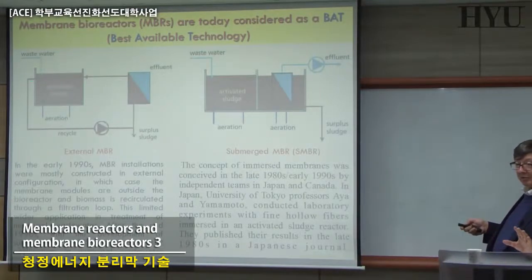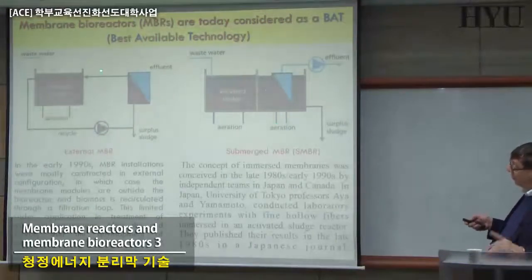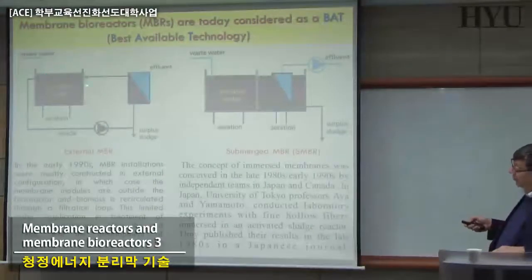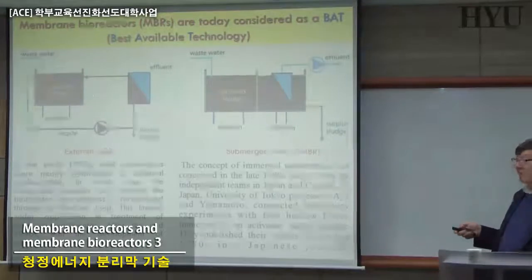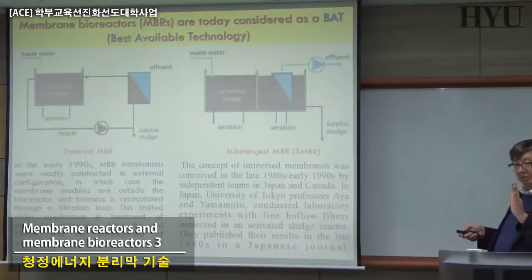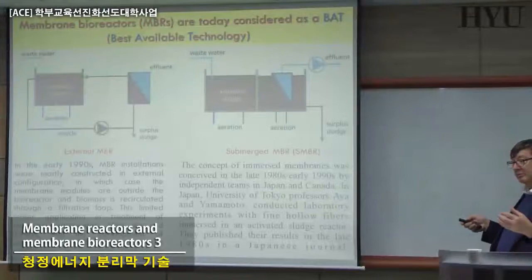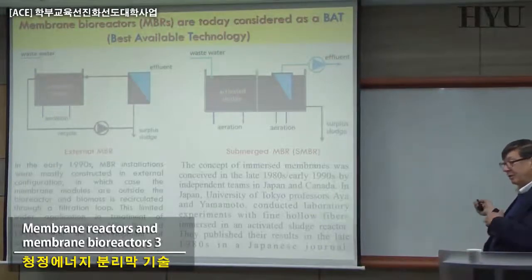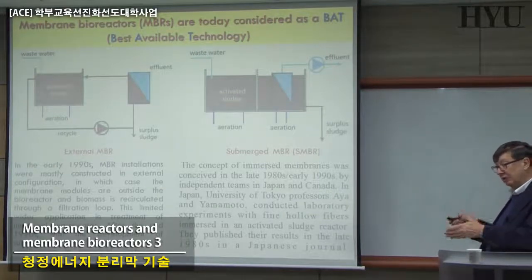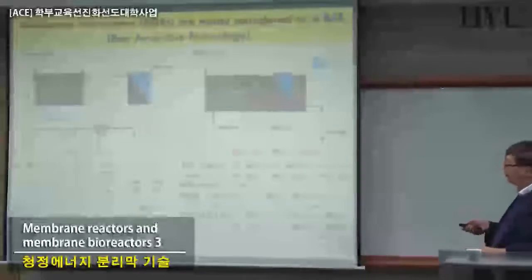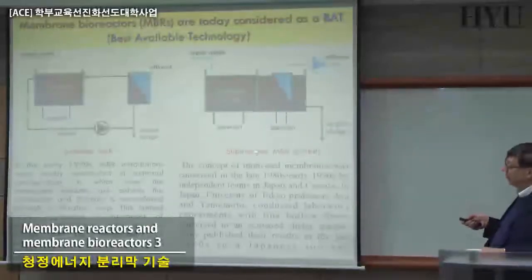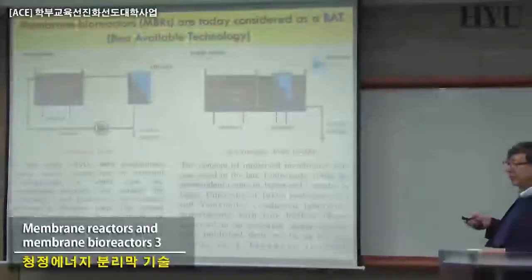So exactly the same kind of operation, but this is immersed. With one change: if you immerse here, instead of pressurizing, as we are doing here on the membrane surface, you make vacuum inside. By making vacuum inside, you can extract the product inside the membranes, and that is the clean part. You clean already most part of the product, and that is what is called a submerged membrane bioreactor.